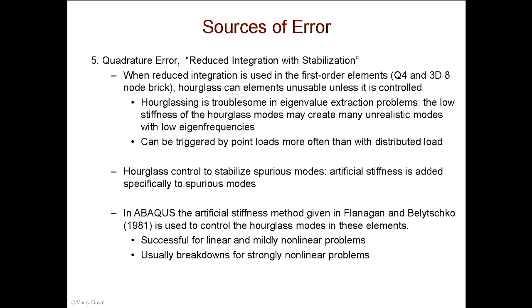So another thing that people do to avoid an error, and Abaqus has this approach, is, as I showed you, reduced integration can result in a problem. And so what Abaqus does, or many of these codes do, they provide you something called Hourglass Control. It allows you to add stiffness that's artificial. It's made up to some level. And the idea of adding this artificial stiffness is to suppress the spurious modes that occur. Okay? And so by adding this artificial stiffness, you're able to mitigate these concerns.